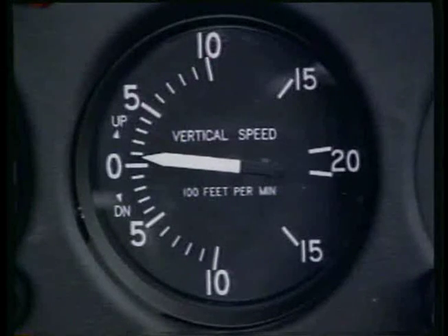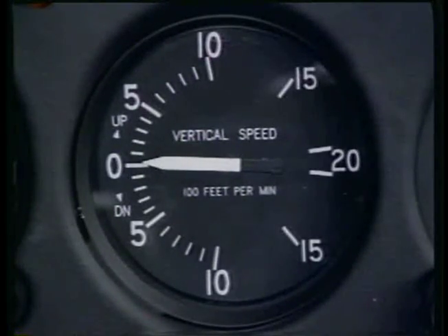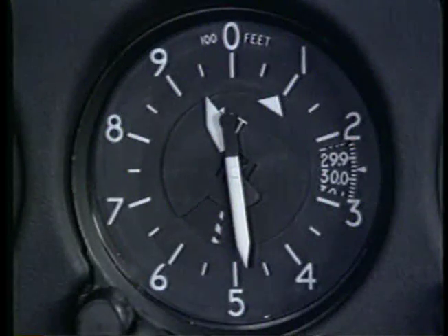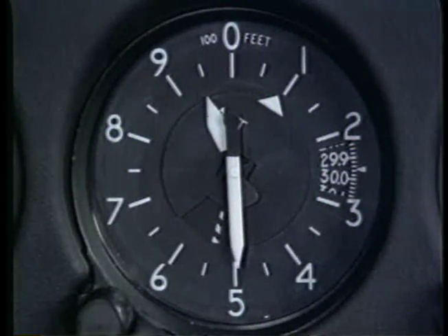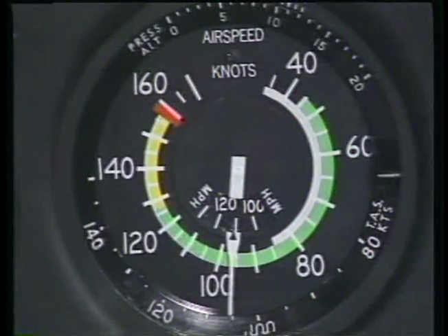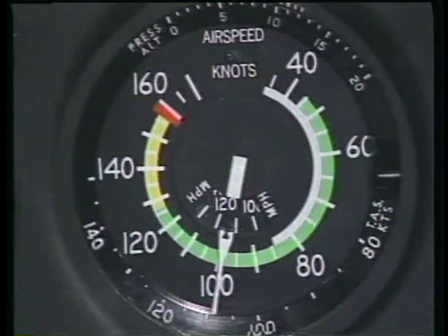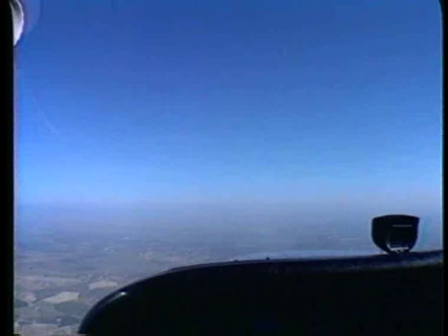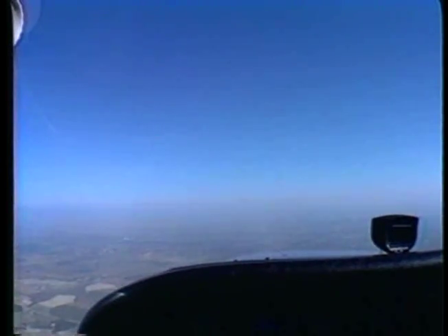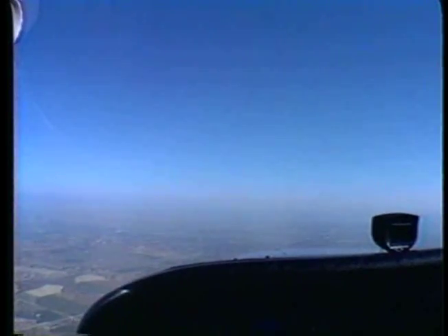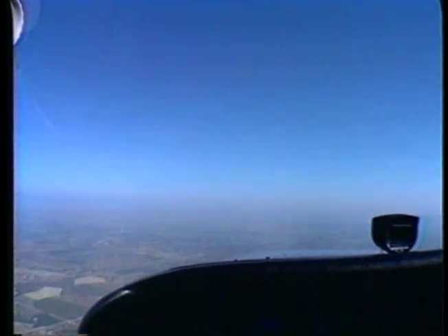As you establish a level flight attitude, the vertical speed indicator will move slowly toward zero. The altimeter needle will slow its upward movement, and the airspeed indicator will move toward cruise airspeed. To complete the transition from climb to cruise, relax the right rudder pressure you held during the climb to maintain the planned heading, reduce power to cruise, and trim the airplane.